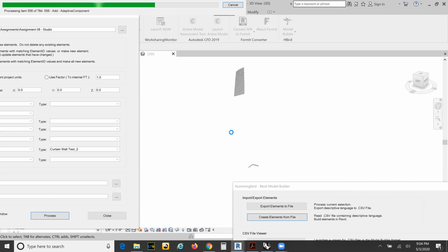But you can see it does sometimes take a bit, but it's just a lot faster than 3D modeling it. And again, these are all the adaptive components. The great thing is, if we change one, we change them all. So if we want to change the thickness of some, we can do that. Now, sometimes one face will be flipped. Of course, there's always something with generating things. Sometimes a face will flip the wrong way.